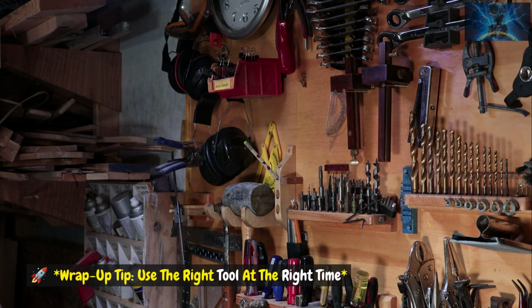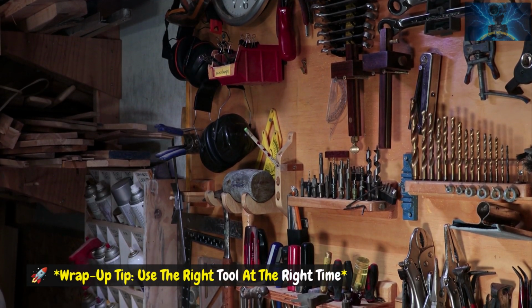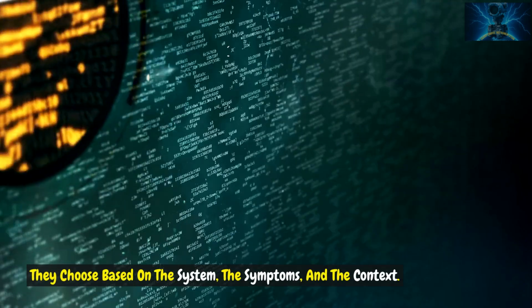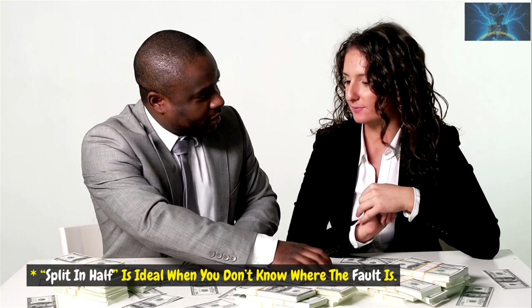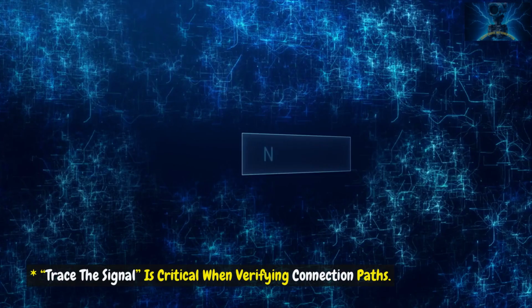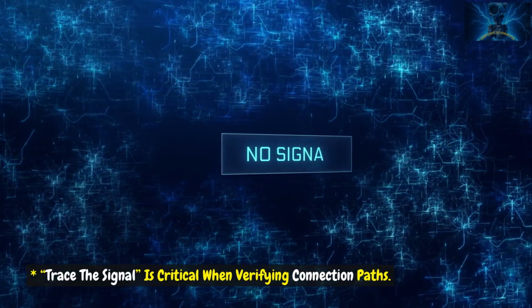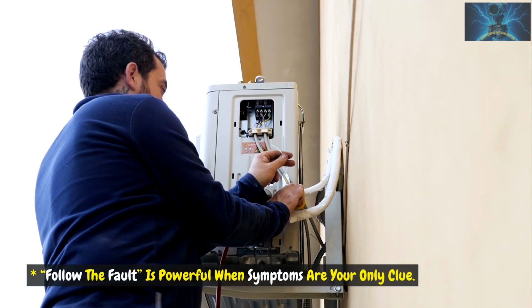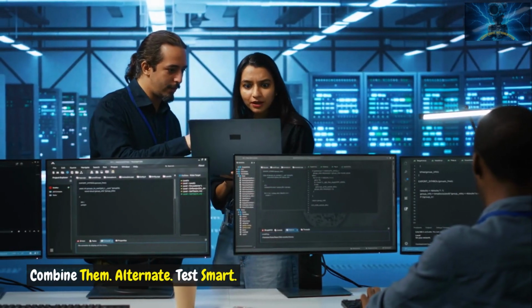Wrap-up tip: use the right tool at the right time. Smart techs don't use one method for every job. They choose based on the system, the symptoms, and the context. Split in half is ideal when you don't know where the fault is. Swap it out is great for uncertain components. Trace the signal is critical when verifying connection paths. Follow the fault is powerful when symptoms are your only clue. Combine them, alternate, test smart.